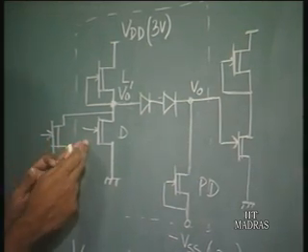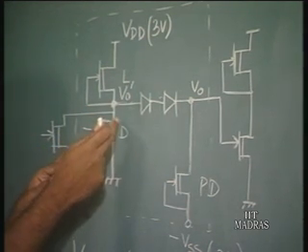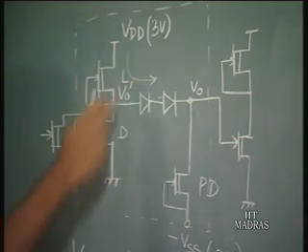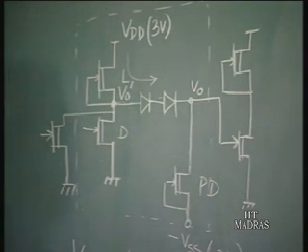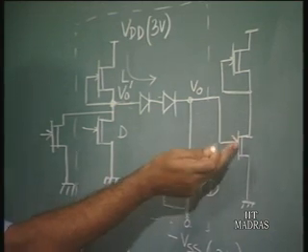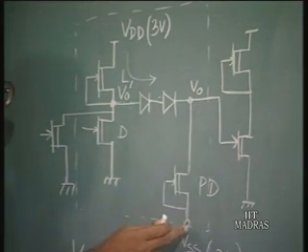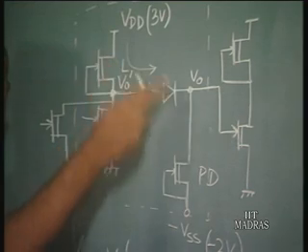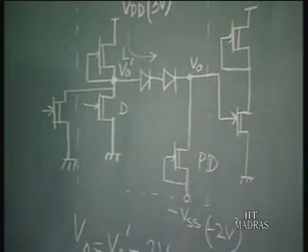both these transistors go off, all right, then what happens is the pull up has to be taken care of by this load transistor. So the load transistor must drive a current here in order to charge the output voltage, or turn on the output transistor, the next transistor here. So it has to supply a large current, but since the pull down transistor is always on, a large part of the current flows into the pull down transistor, and thereby the delay is quite high.